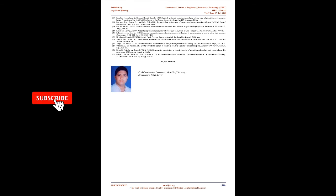7. Conclusions. The following can be understood from the findings of this analytical investigation. 1. For NSC connections, the ultimate failure load of the connection where the distance between the center lines of the beam and column equals 15% of column depth is less than that of the reference connection by about 54%, while the ultimate failure load is reduced by about 5% for the same HSC connections. 2. For NSC connections, the ultimate failure load of the connection with the beam side at the column edge is less than that of the reference connection by about 55%, while the ultimate failure load is reduced by about 25% for the same HSC connections.